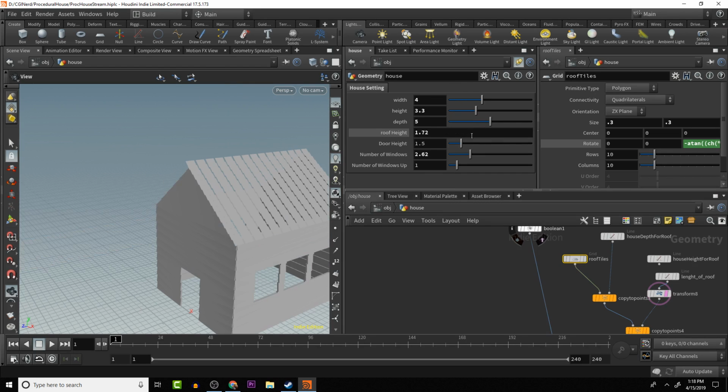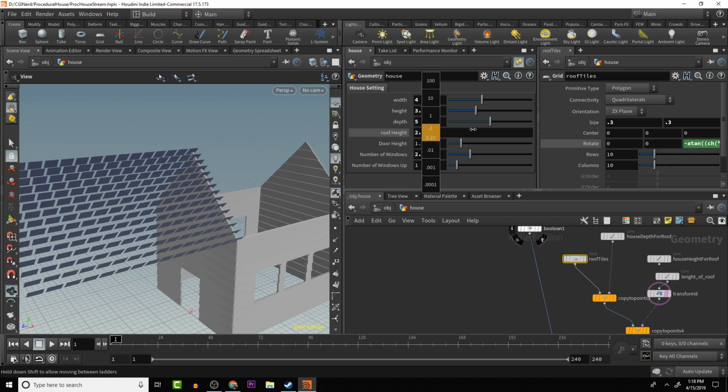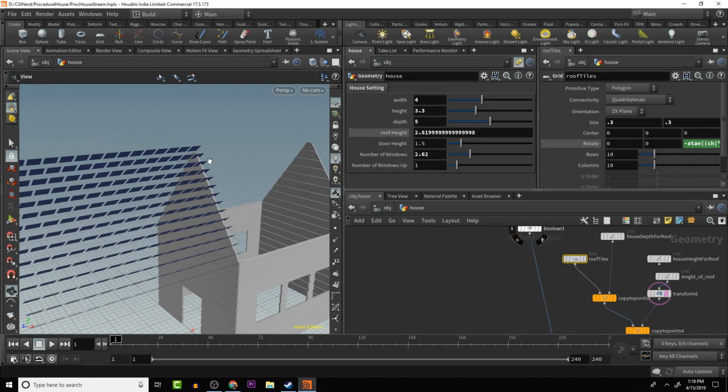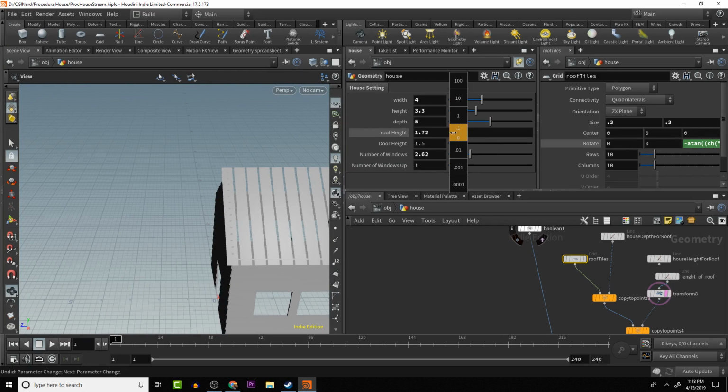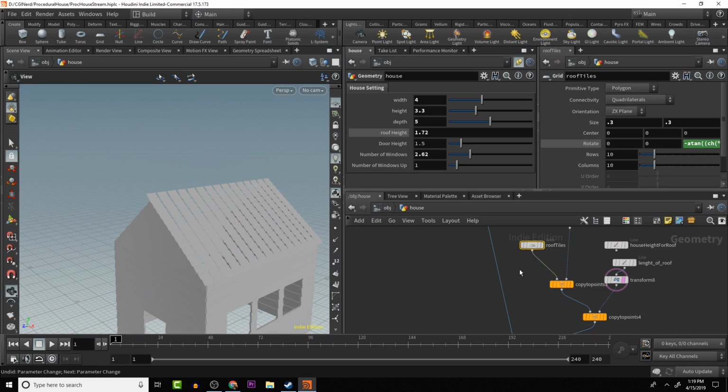Oh, there's something breaking there. We can adjust it in a little bit, but let's not do big values. Let's do here. What's going on? Okay, it flips on us. So we have the default values, it's fine. Oh, okay, I know what's going on. We have the points set up, but on this line, it doesn't have a normal direction, so it doesn't know which way to actually create it as the values change, so it kind of flips back and forth.